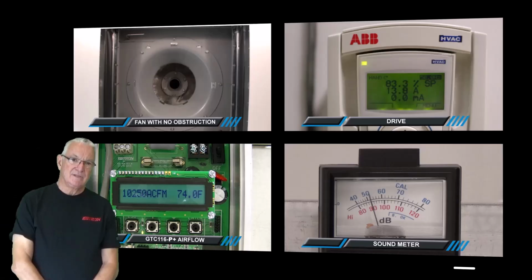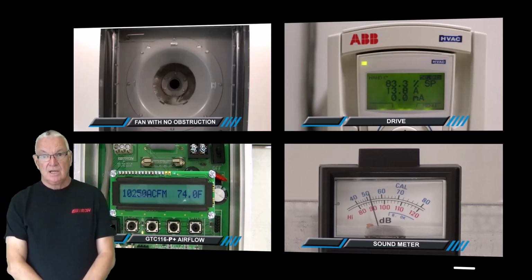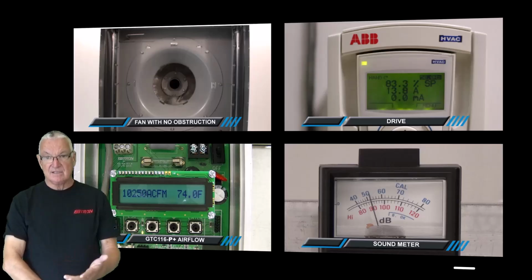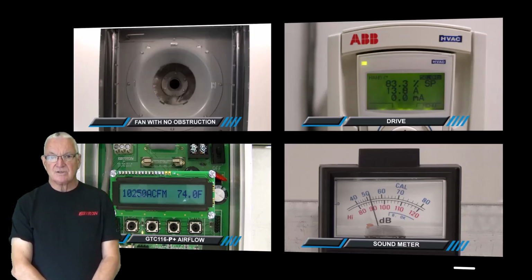This is a plenum fan with nothing in the inlet, and it's showing you what a flow meter reference ducted downstream of this unit reads, and what the current draw from the drive is, and the sound level. So we'll just go over here. We've got the fan, nothing in it. We have the motor drive that shows 13.8 amps. And what our fan speed was set to, in this case, was 83.3%. The total supply airflow was 10,250 CFM, and the sound level was 90 dBs.